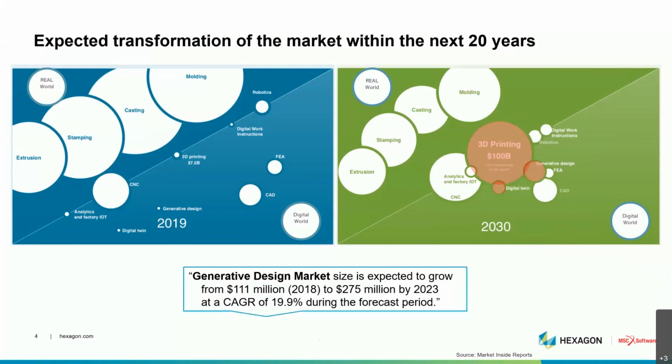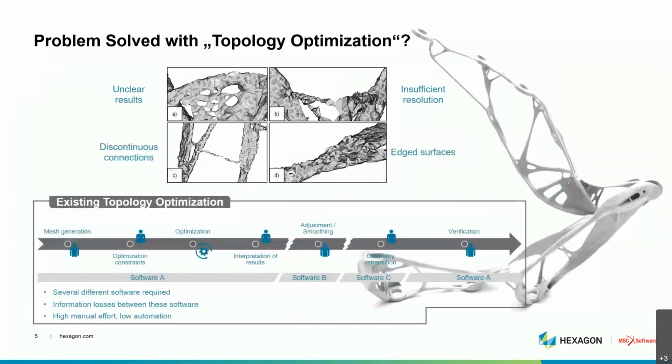We talk about CAE, generative design, etc. I think many people will think directly about optimization of structures. And there we all should know the topology optimization technology. Topology optimization is quite a good technology based on finite element methods, where you start with a big block of design, put your loads on it, constraints, and then the overall block is calculated.